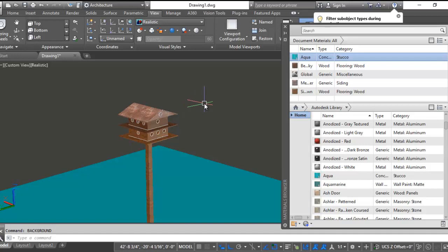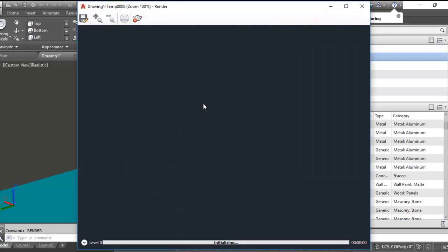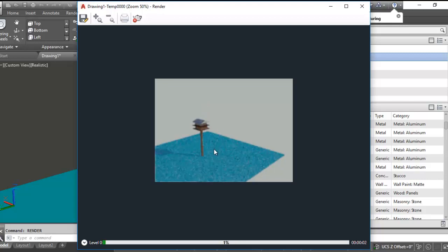The last thing we can do if you want to get real fancy is render. And this does take some time depending on your settings, but when you render, it takes this to a more photorealistic level, and it's just plugging along here 15-16%, and it'll render through this so I have a good presentation quality image. But that's the steps to work through this. The intent here is to get you familiar with the press pull command, applying materials, and then setting up lighting and sun and sky background options as well.